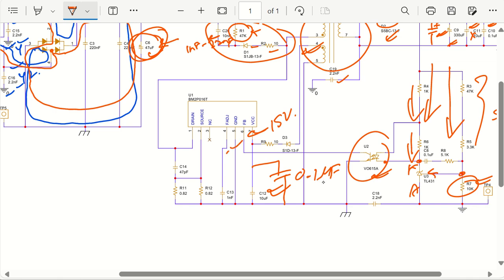This is the ground line, so that is connected here. Then we have the F adjustment that I already told you about. We had frequency hopping, or frequency reduction, and burst mode. So all these things were there. For that, one capacitor is needed, which is 1 nanofarad.